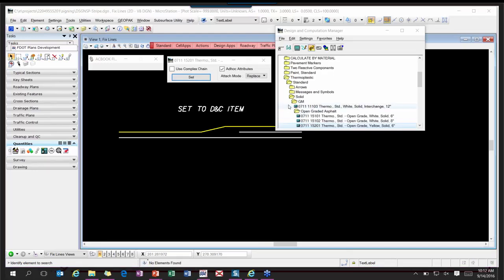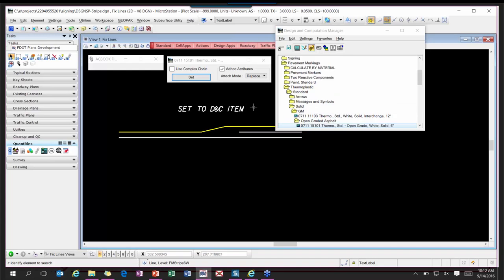All right, and I can ID this and look at it. And if I want to verify the ad hocs that are associated with this element, did they get on there? In our workspace, we have turned off the ability to see that, okay? Because especially with a lot of the cells that we place, there's some items that are out here that all you have to do is just hover over it and it would crash MicroStation. So we have a configuration variable that turns all that off, and you want it to be off. It's not worth it to have everything just crashing all the time.